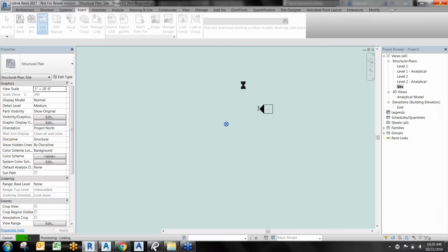So this is also a lot of information, and just a forewarning, try to keep your surface as minimal as possible for your site, because all that information, you can clip things and delineate work sets in Revit, but it's always better to go back to that source, fix it up, just like if you were to bring in a section detail from AutoCAD into Revit, you'd want to clean up those layers, clean up everything as possible, and then bring it in here.